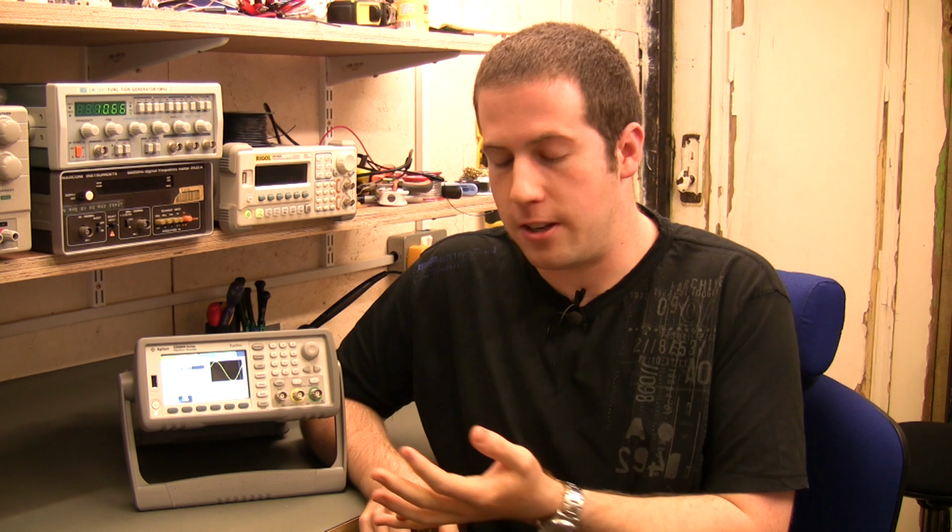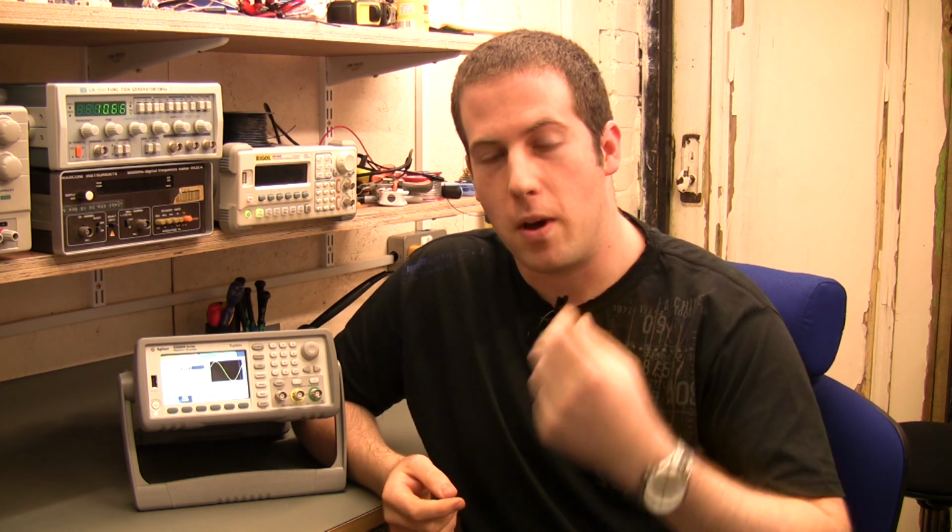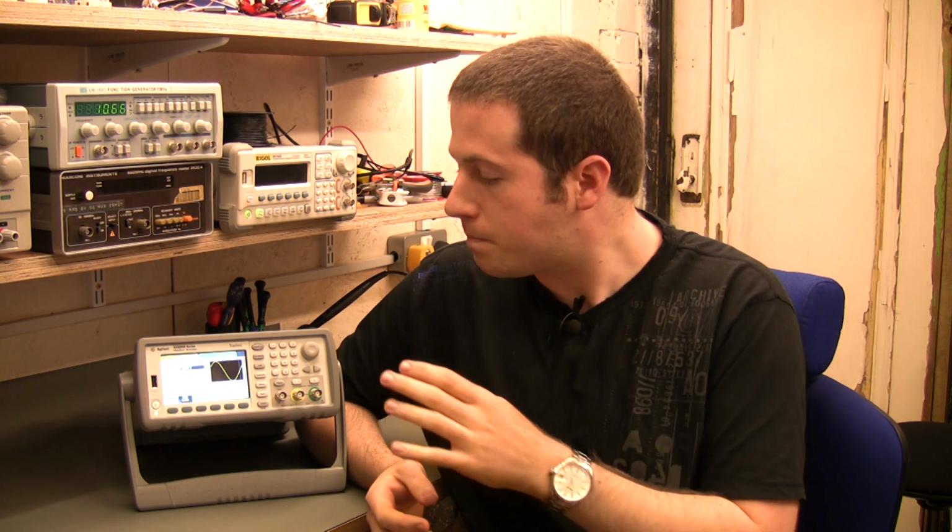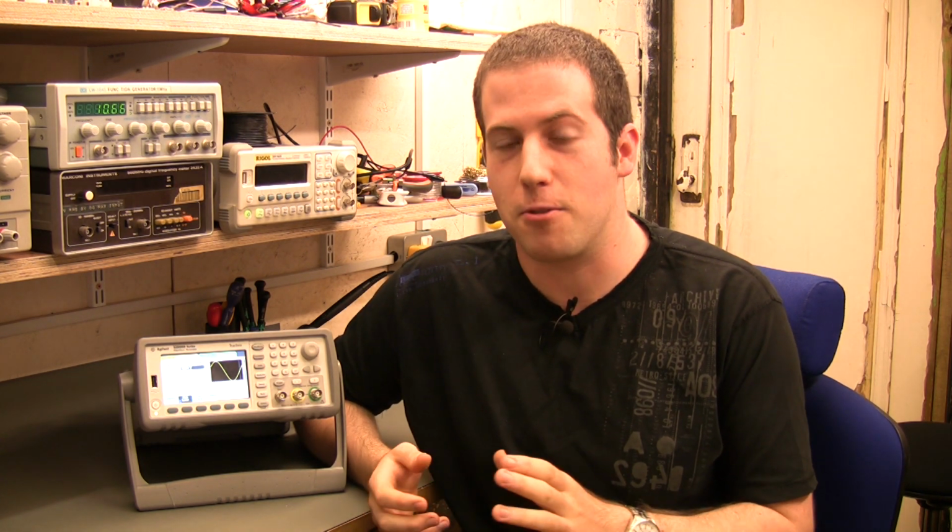And something that comes up a lot for us, and something I use at work, is thermal batteries, where there's an electrolyte that's made out of metal, and you melt it by having a very, very high temperature on there, powered by pyrotechnics. When that melts, that powers up a circuit because it functions as a battery. The problem is, every time you set off one of those thermal batteries, they're very much non-reusable, and it's several hundred pounds down the drain. You don't want to do it all the time for circuit development. You have one of these, you run a thermal battery once, you capture the voltage output, you play it back on this repeatedly, you get your circuit development 99% of the way there, then you just finish it off by trying it with some real thermal batteries. That's going to pay for itself very quickly, and things like the 16 meg of memory allow you to do good 15-minute playback times, which is absolutely amazing.